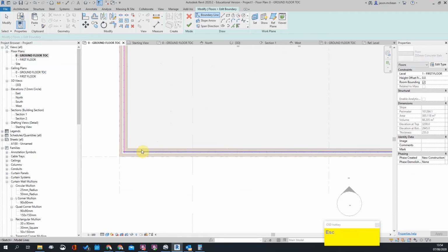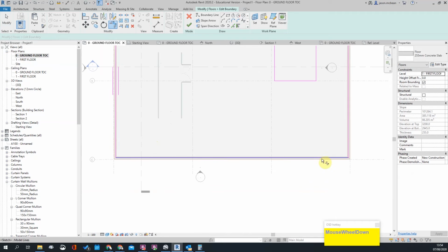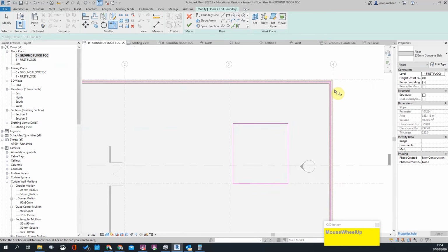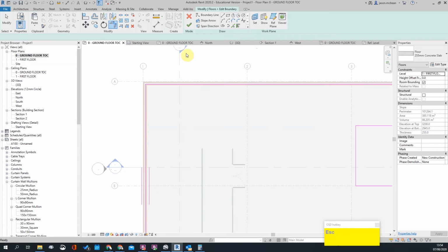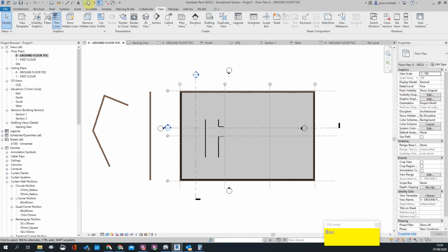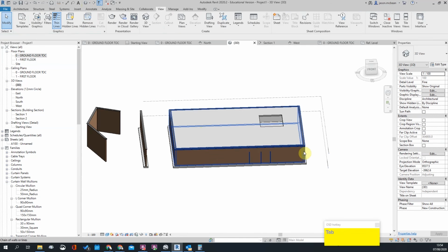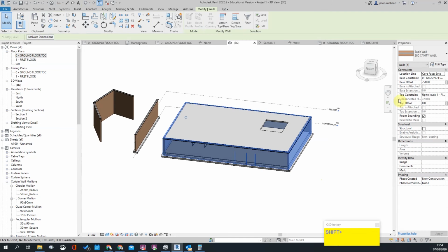Okay, so the internal brickwork gets built up to the underside of the slab. The external skin will sail past, and you put steel hangers that will carry the external skin. Okay, so finish. I'm just going to grab, so tab to select, like you would select a whole bunch of connected line work, same story. I'm just going to extend this past by 2 meters.